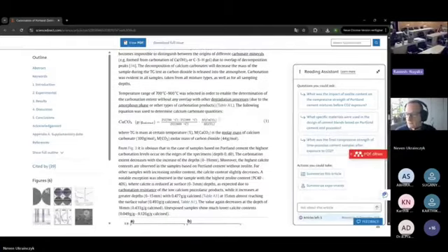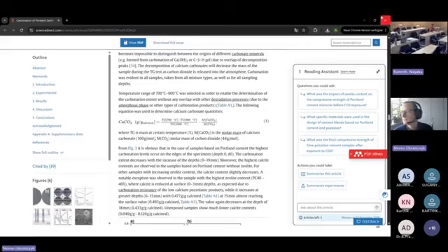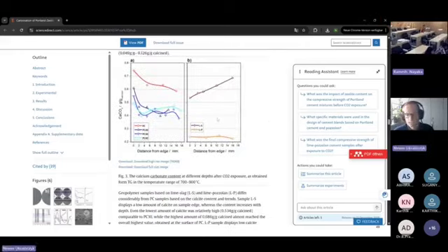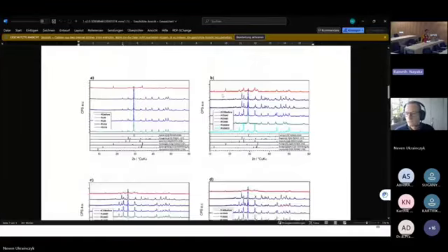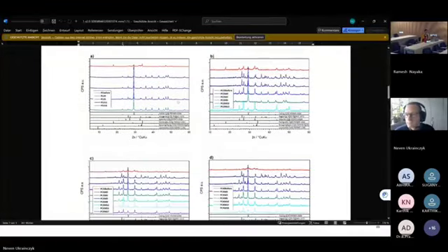Sorry to interrupt you. I had one more query seeing the XRD graphs, sir. We have been trying carbonation with different pressures, and if we see the XRD results, the peaks have not shifted much, but there is a difference in intensities. Can we attribute this to the carbonation? But do you see this calcium carbonate peak? Yes, sir. Calcium carbonate peaks are there, but the major peaks have not shifted much, but there is a difference in the intensities. Yeah, the intensity shows you it's proportional.